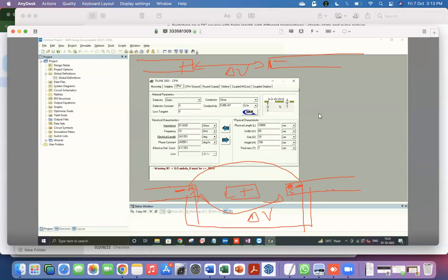So there is one other aspect of the slot line mode, which is that it's a differential mode because it's like plus minus, there is no ground. So for two terminal devices, sometimes it's useful to have these kind of modes. And I actually, back in my grad school days, did use a circuit which had a slot line coming from a CPW, actually a transition from a CPW to a slot line mode, because I wanted only two conductors to be present. And the CPW ideally has three.